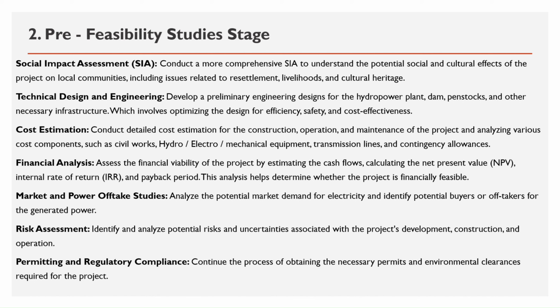Technical design and engineering. Develop preliminary engineering designs for the hydropower plant, dam, penstocks, and other necessary infrastructure, which involves optimizing the design for efficiency, safety, and cost effectiveness. Cost estimation. Conduct detailed cost estimation for the construction, operation, and maintenance of the project, analyzing various cost components, such as civil works, hydro-electromechanical equipment, transmission lines, and contingency allowances.